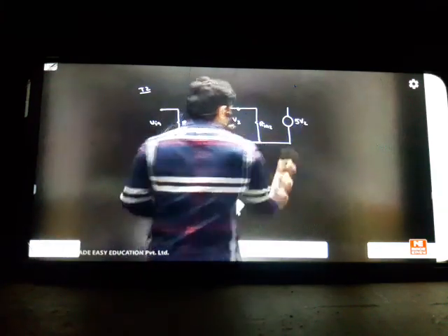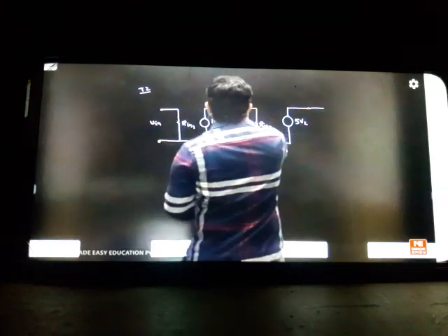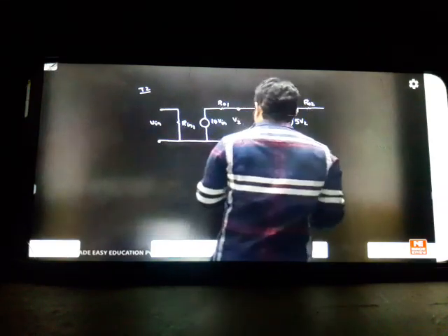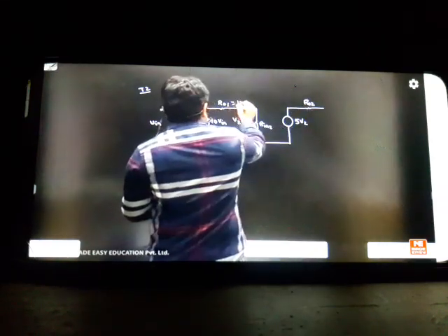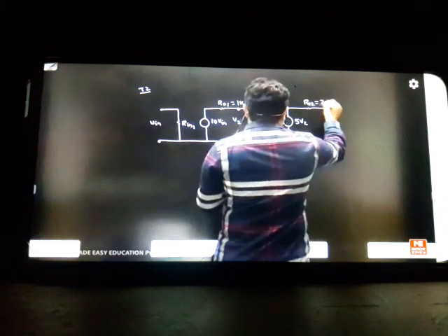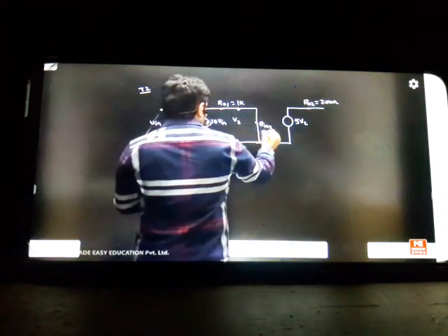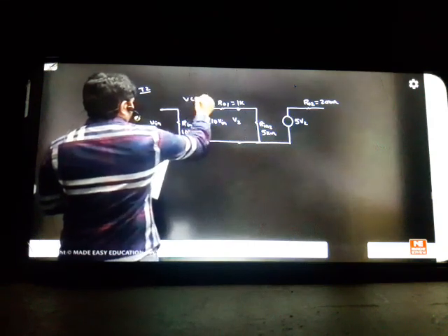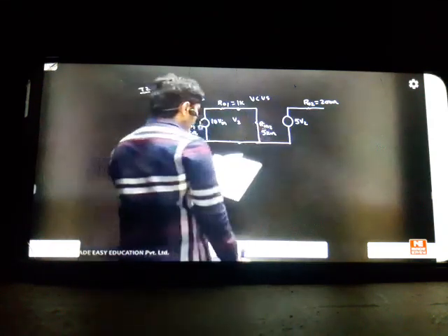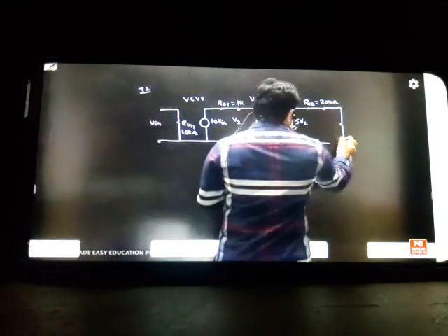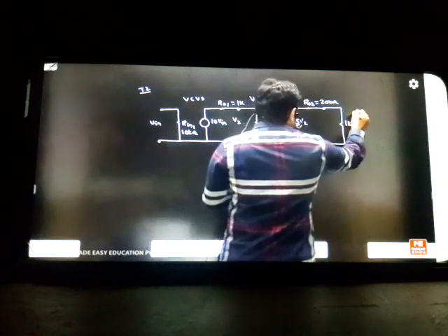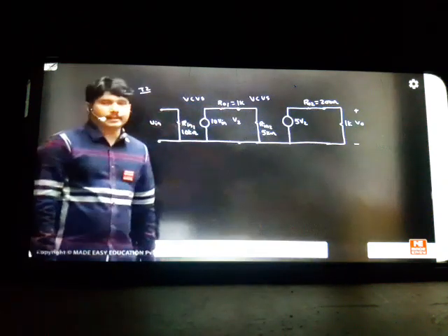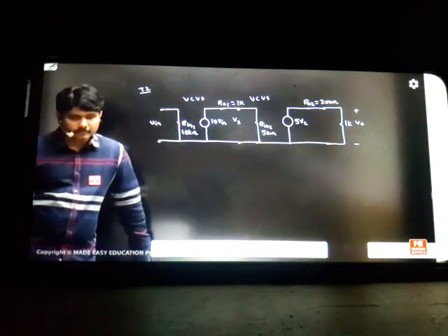This will be V2. Next we have a resistance here R01. This you take as R02. R01 is 1K. R02 is 200 ohms. R_IN2 is 5 kilo ohms. And R_IN1 is 10 kilo ohms. Just write the voltage controlled voltage source models. But in this question what he has done is, he finally connected a load here. Load he connected as 1K. In the previous question I think load he had not connected. Here we have connected the load.